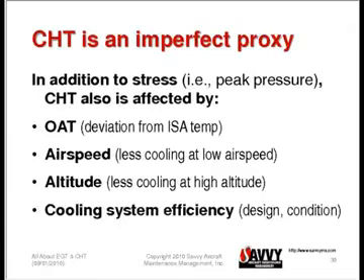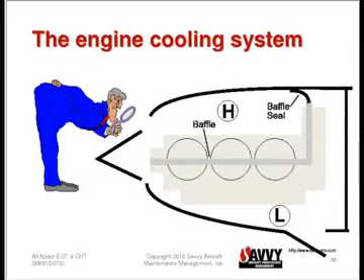Also, of course, the condition of the cooling system makes a big difference. If we have baffles out of place or baffle seals that are not in very good shape, we're going to have higher CHTs simply because our cooling system is not in a state of good repair. And these are all things that affect CHT in addition to the stress on the engine. So we have to take those things into account.